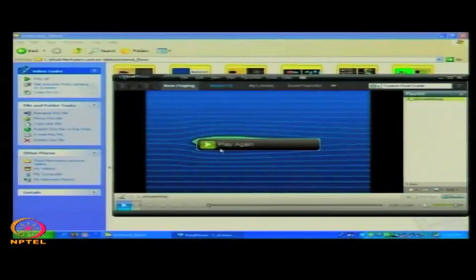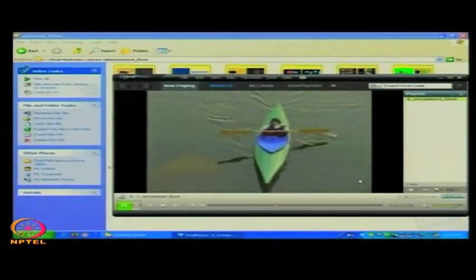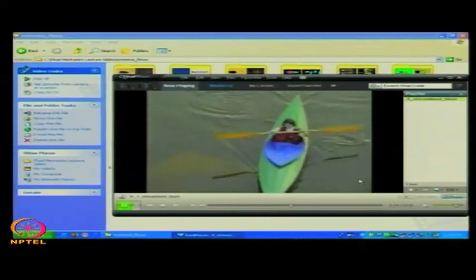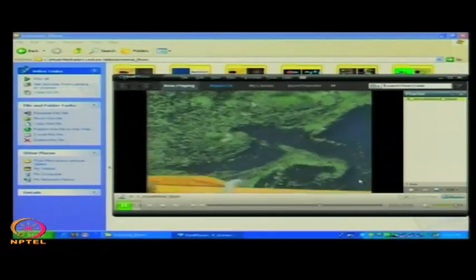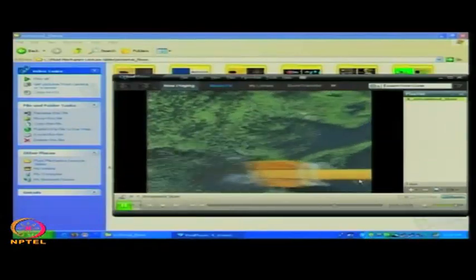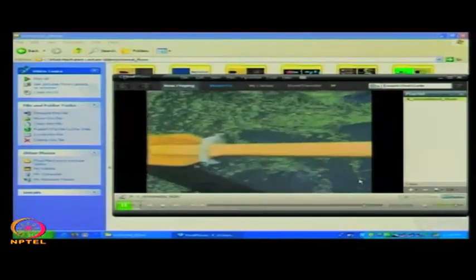So, a streamline body will have a much lesser tendency of boundary layer separation. Let us try to see an example where we have a combination of streamline and bluff body. The boat that is moving is like a streamline shape, and it is sailing fine in the water, but if you see closely the flow around the stern, this is quite bluff, and the flow around that has the effect of flow past a bluff body.